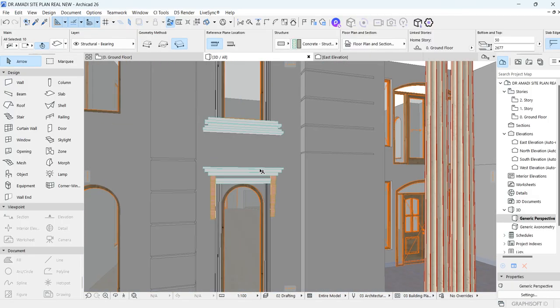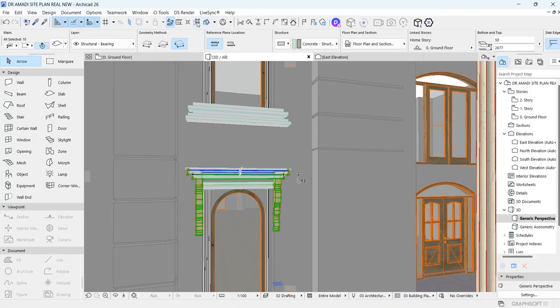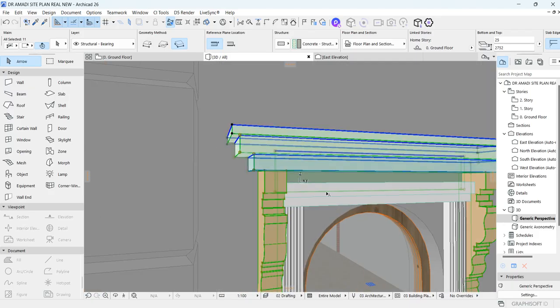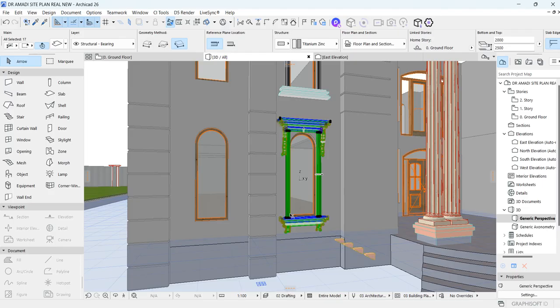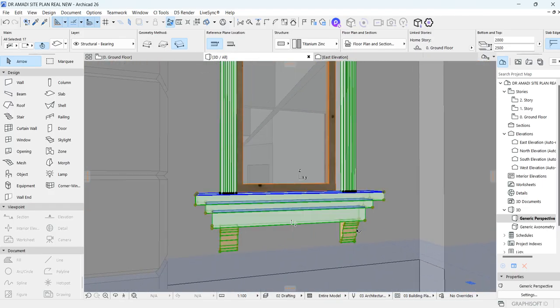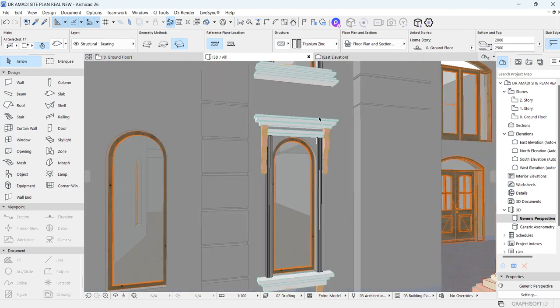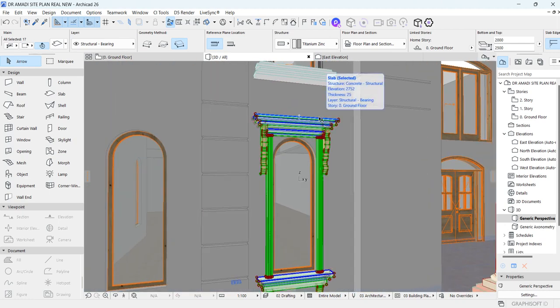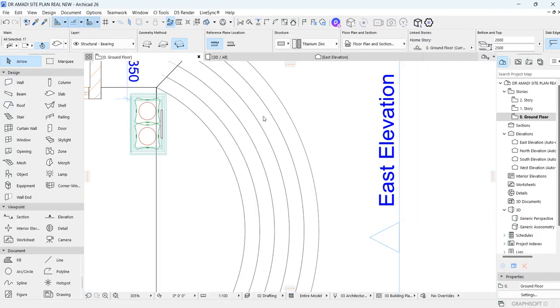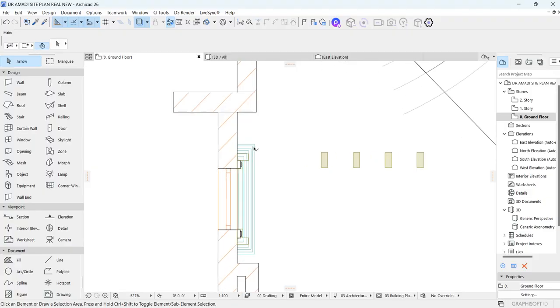So let's think of how we can duplicate. I've clicked on this office suspend group, and let's add the other slab too because I have to modify this. Let's add and group them together. I'm holding shift so that I can select them. I think every other one here is included. Then I will press Control plus G at the same time. So it's grouped, and I can easily copy from this one.